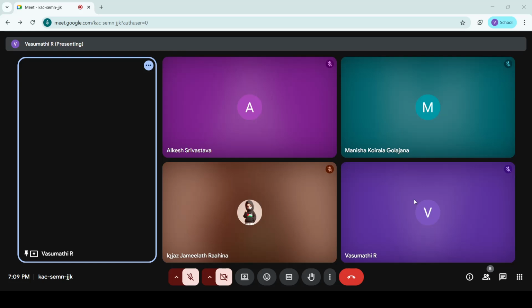Okay. For voltage divider rule, the denominator will be R plus, since this L and C are in parallel, I am considering it as a parallel. We will expand it later. For simplicity, I am keeping it as a parallel as it is. For current divider rule also, this will be the same, R plus L parallel to C. If these both are connected in series, then it will be L plus C. Since both are in a parallel combination, I am writing it here. For voltage divider rule, the numerator will be this term, L parallel to C. For current divider rule, the numerator will be this term, that's it. That is the difference between these two. I hope this is clear.